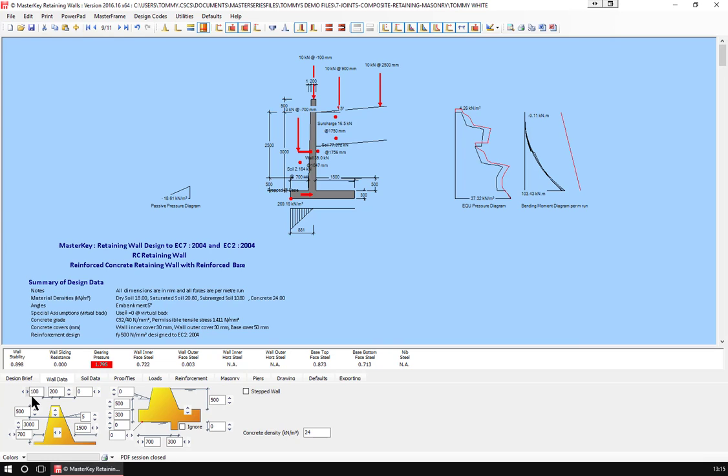It's got a 500 upstand above the soil, so we can take our wall higher than our soil, either to put wind onto or to make it such that that's the physical wall that's defined, and therefore we are able to use and define it for self-weight and for the reinforcement that's going to be required.